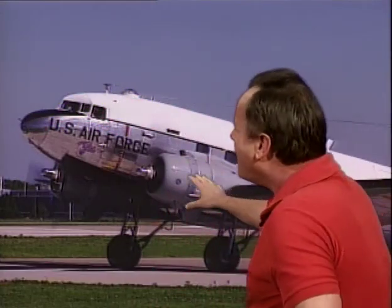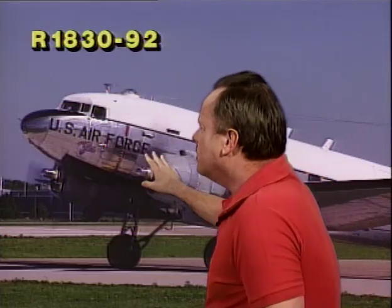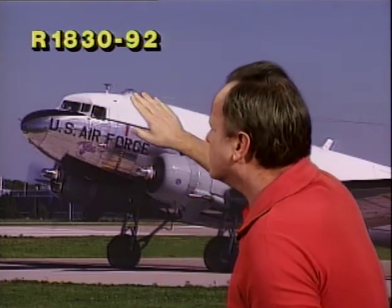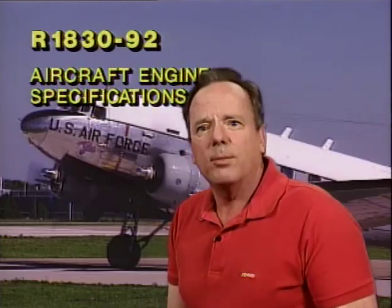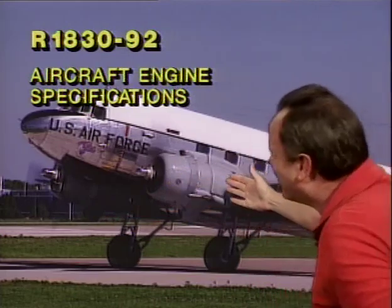Let's assume that you have a DC-3, and on that DC-3 installed is an R1830-92 engine. Now, where would you find the type design information for that particular engine when it's installed on a DC-3? Would you go to the aircraft specifications or would you go to the type certificate data sheets? You would go to the aircraft engine specifications, because DC-3s, as you know, were type certificated before 1958. And you can tell by looking at this, this is one of those older aircraft.